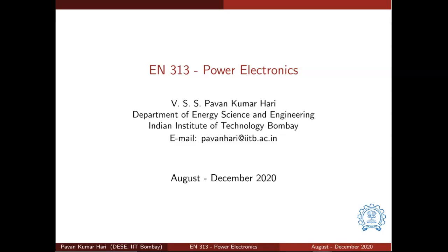These waveform measures can give us a quantitative assessment of the performance of a power converter. Another way to look at the performance of a power converter is in terms of the energy lost in the power converter, or power loss. This will help us determine the efficiency of power conversion. Ideally, we would like to have 100% efficiency, but any real power electronic converter will have efficiency less than that. What is the reason behind that? What are the contributors to the power loss in a power converter?